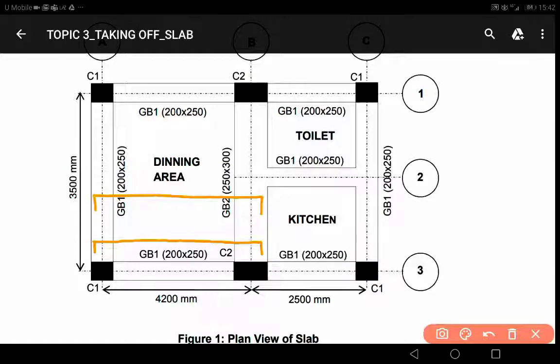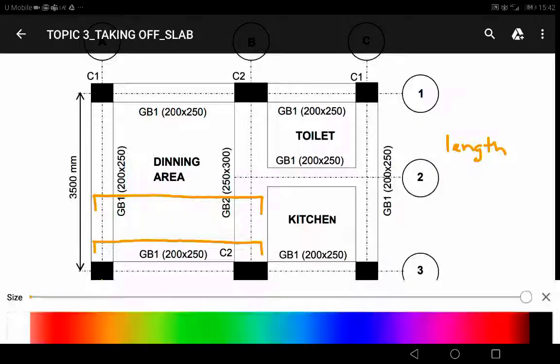Right, so first we are going to determine the length of one reinforcement here. So now you have 4,200 mm, but basically just up to this half beam and half beam here. So if you look at this diagram, your reinforcement is more than 4,200, and if you notice here it will be the cover, here it will be the cover, so meaning that it has two cover.